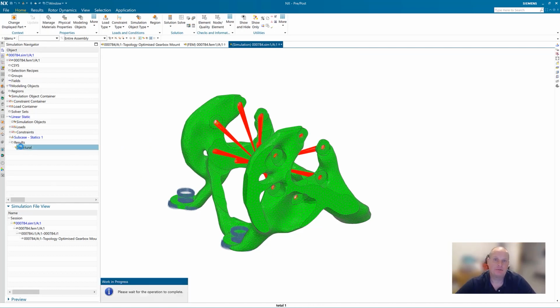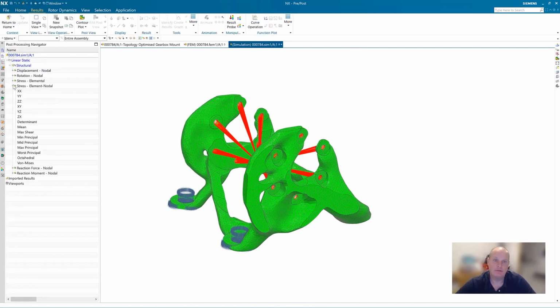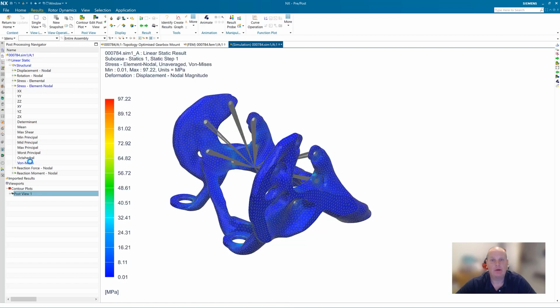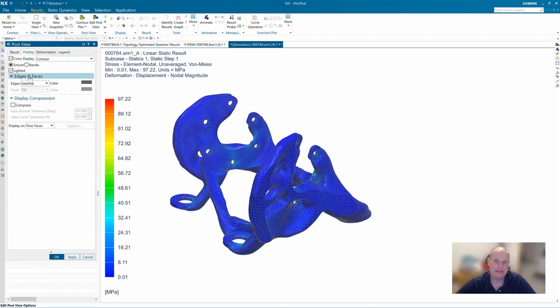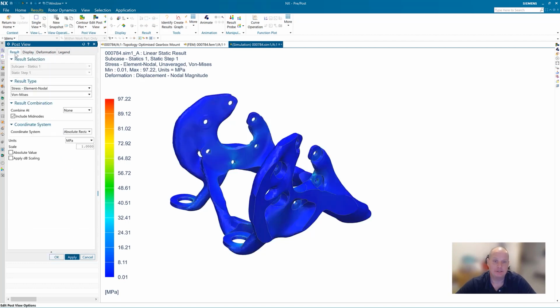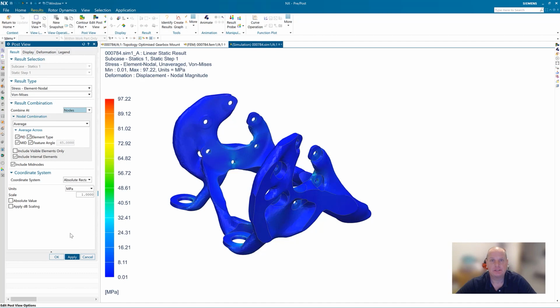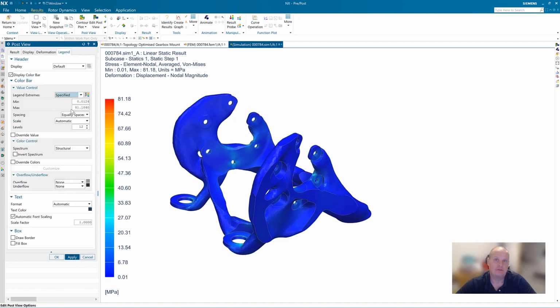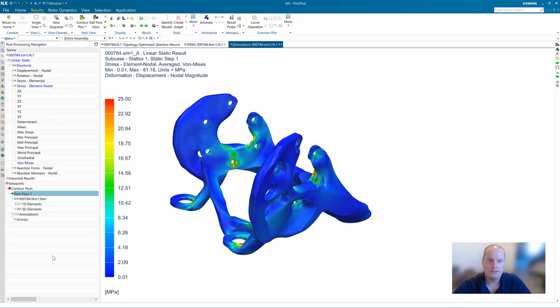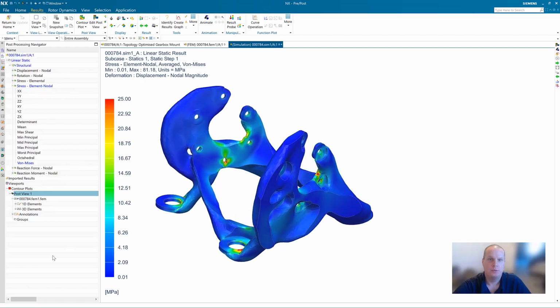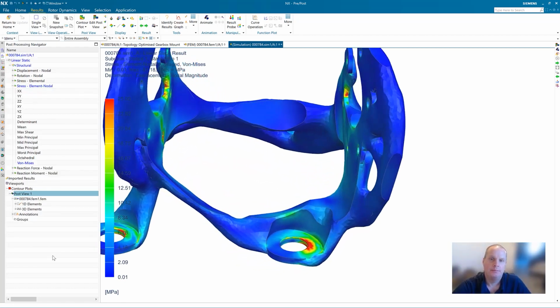Now comes the reason for performing the analysis, evaluating the results, and giving recommendations to your CAD designer. When displaying stress results, it is a good idea to turn off any elements that are not needed, clean up the display by turning off element edges, setting the results to average at nodes, and finally changing the scale for effect. Let's interrogate the CAE results so we can make recommendations to Paul.